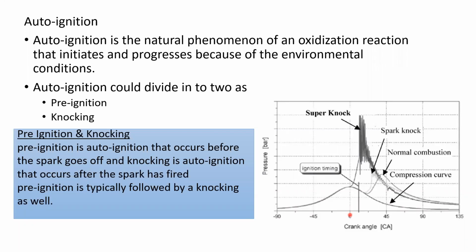If you use a hot plug in a cold plug location, that will create a problem: it will automatically ignite at a certain pressure. So it could actually ignite before the correct position, and the combustion will not reach the maximum pressure necessary. So it will generate a lot less power.